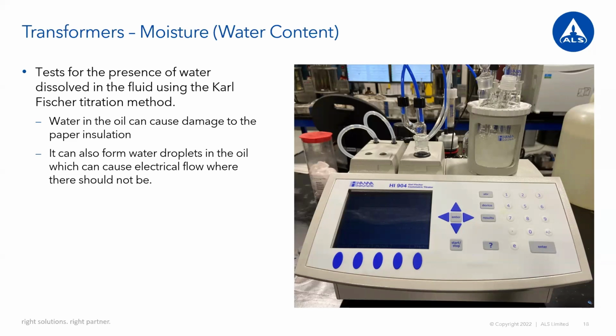Now, the good thing with the ester fluids is we don't need to worry so much about moisture, because ester fluids have open oxygen bonds. It can actually suck in the water. So water content for oil no higher than 35. Water content for in-service ester fluids 400 ppm.